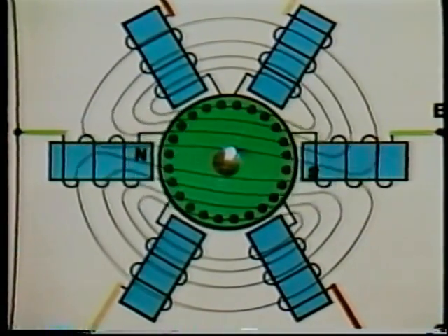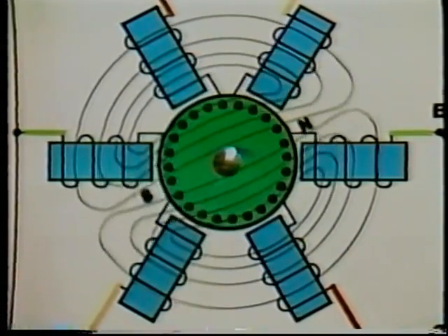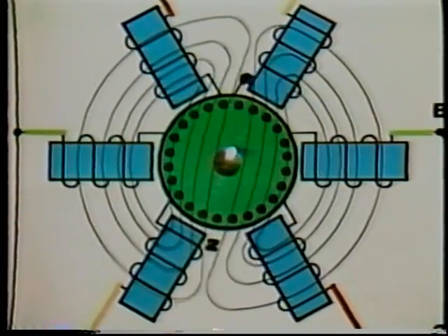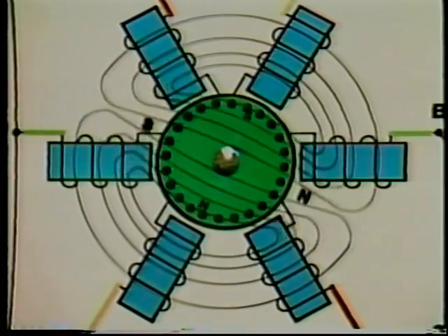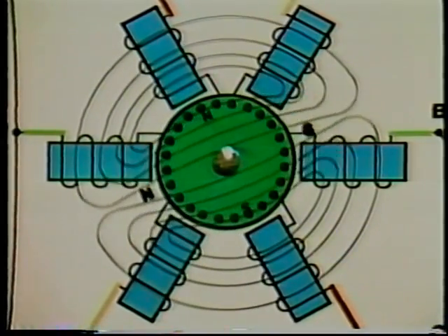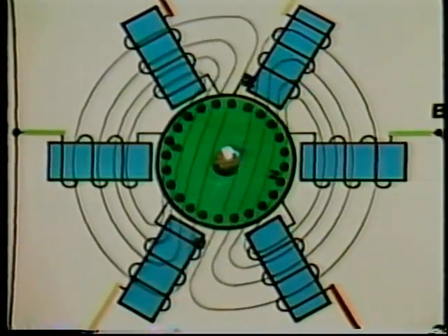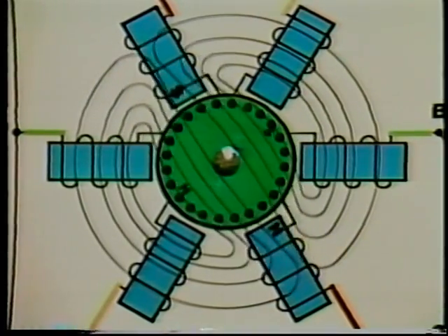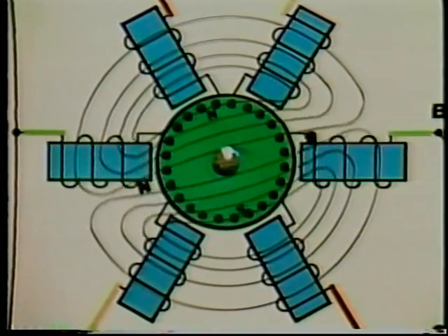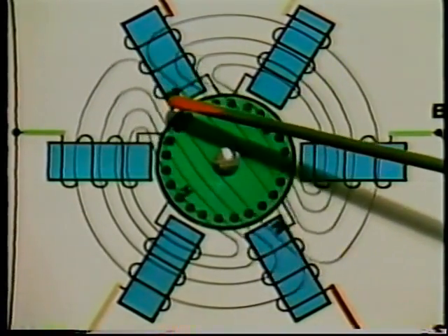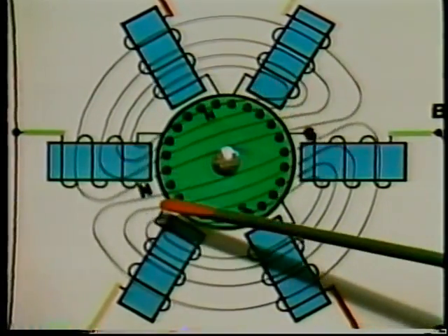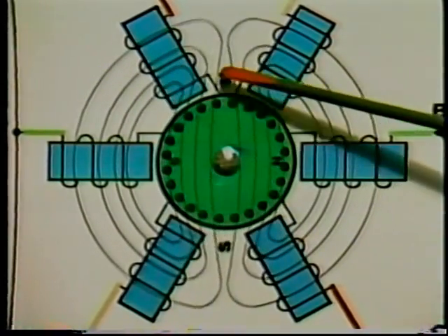Resistance is low, and high currents flow in the conductors. These rotor currents produce strong rotor poles, which follow around the motor between the stator poles. Each rotor pole is pushed by the stator pole behind it and pulled by the stator pole ahead of it, so the motor exerts torque.